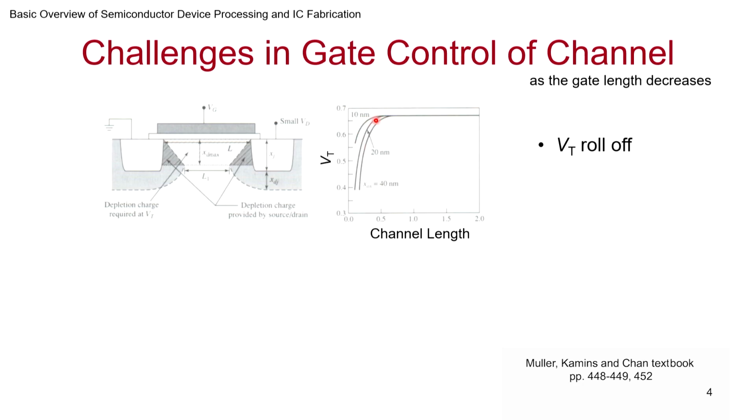So what it means is, if there is a small process variation, your threshold voltage will vary like crazy. But not just that, your threshold voltage comes down. So that means many times you cannot turn off the transistor properly. Usually we use 0 voltage for turning off, so you'll find that you won't be able to turn off, and there'll be a lot of leakage current. So this VT roll off, as it is called, is a big challenge.